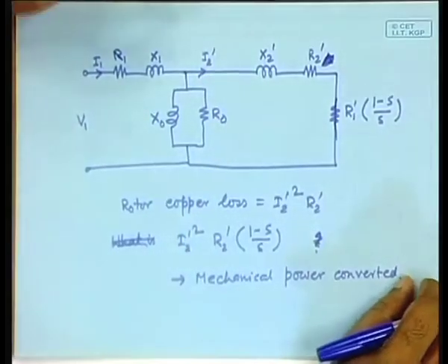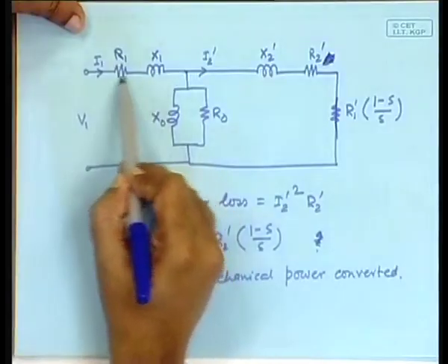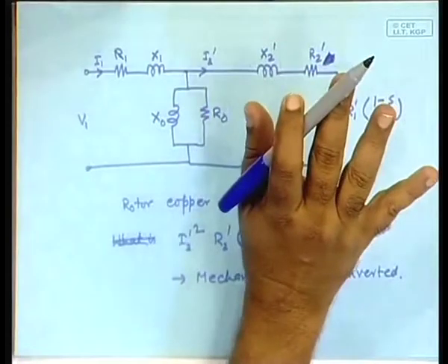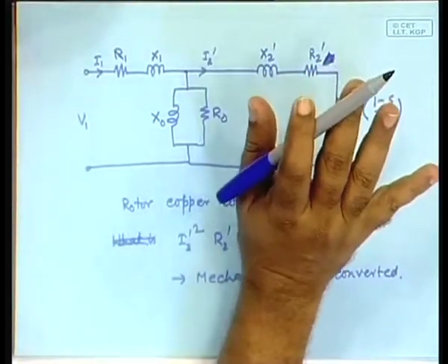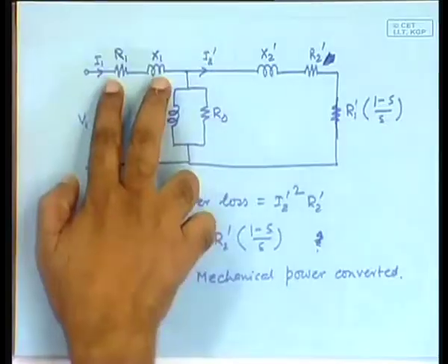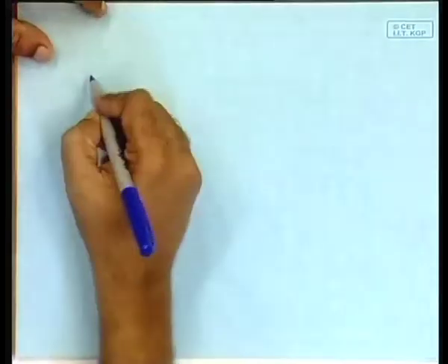So, what electrical engineers do is to assume that the sky will not fall on our heads if these 2 things are moved to this side. Yes, it will incur a bit of inaccuracy, but that inaccuracy is to the extent of 10% only. So, we tolerate that. We move these 2 to this side, and as a result the approximate equivalent circuit becomes,